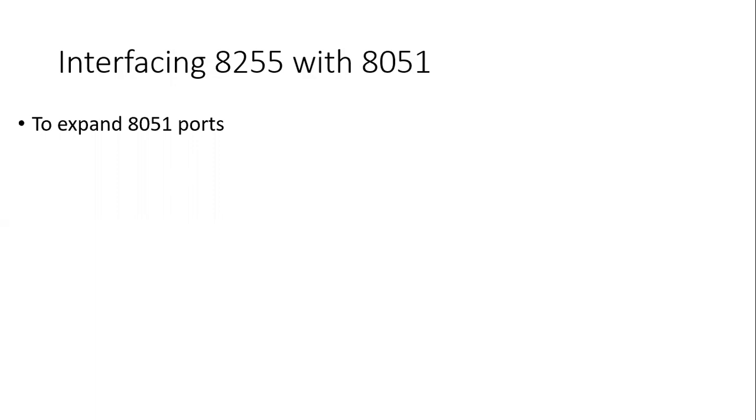8255 is called a programmable peripheral interface. So using this, we can connect many peripherals to the 8051. 8255 will act as an intermediary between 8051 and the peripherals in a way that expands the ports of 8051, so that many peripherals can be connected to 8051 in parallel.